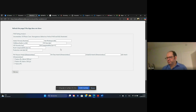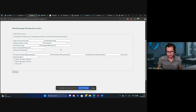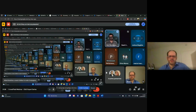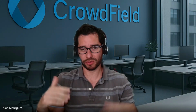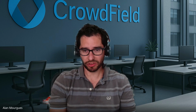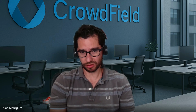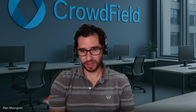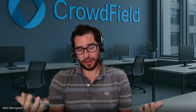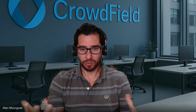If you see what I mean. Yeah, but you're matching against that. This is what I'm not getting. Let me go back one step further. If I were to do a pressure transient analysis the traditional way, the deterministic manual approach, I have my data, I load it to the software, I have my history plot, I have my derivative, and then I tweak my KH, skin and distances to barriers or limits. Sometimes the data suggests that there could be more than one model that matches the data, or combinations of parameters that match the data.